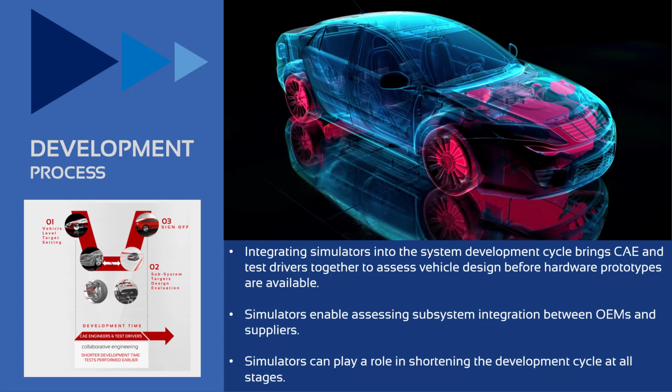It also allows for an earlier and more effective sharing between OEMs and suppliers, where both entities can assess design intent with a driver-in-the-loop process. This can be done at the system level, starting with target equivalent models, proceeding with software-in-the-loop evaluations, and finally with hardware-in-the-loop validation if needed. The development cycle can be shortened because the component and system level sign-off can be done with simulators in a consistent way with how targets were set, and without waiting for expensive, in cost and time, mule or prototype builds for testing.